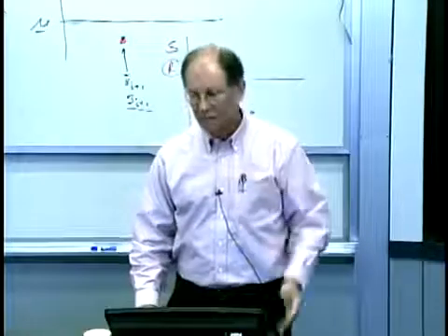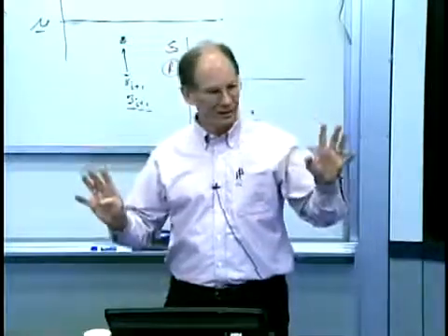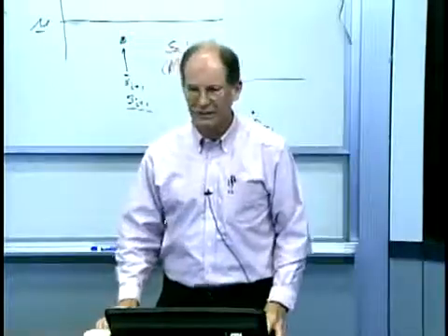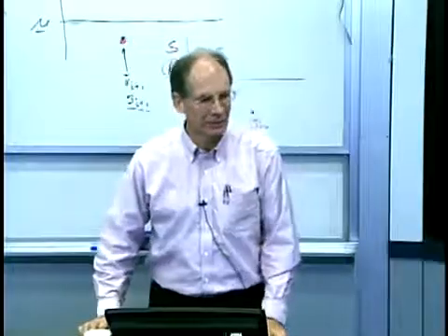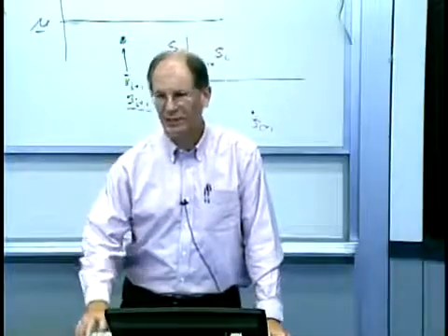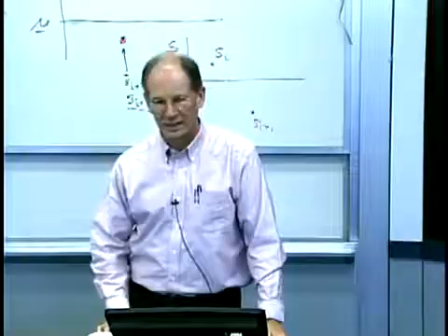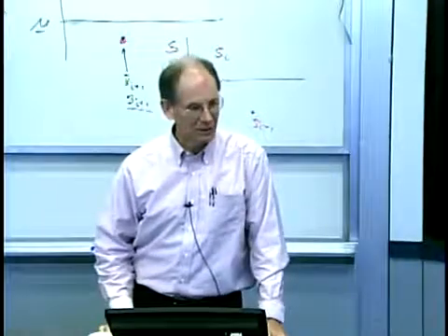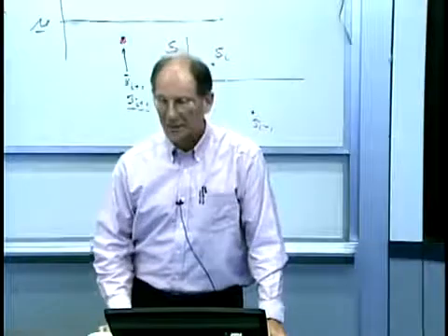Okay, so test for out of control. I think this comes out to 8. If you have a set of data and you look at it, the first thing you might do is ask, is anything outside the plus or minus 3 sigma limits? That's really unlikely. If I get any extreme points like that, pull the andon cord, stop the production, something's wrong. Let's go out and fix it.